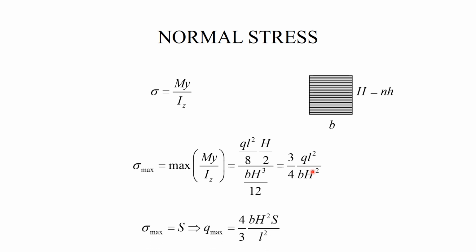Now we can use the maximum stress to compute the maximum Q. All we have to do is equate sigma max to the strength, and this gives us the expression for the maximum load the beam can sustain.